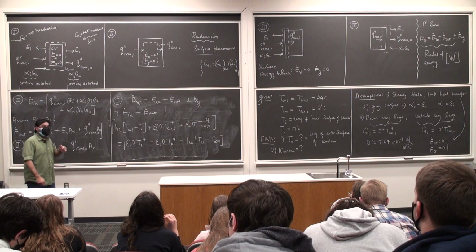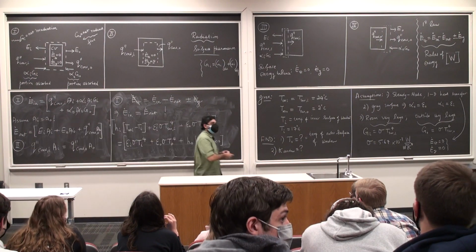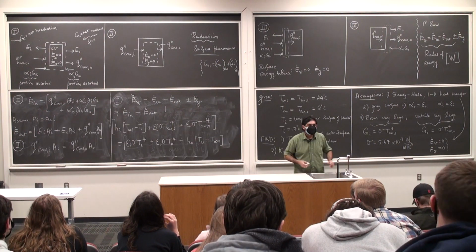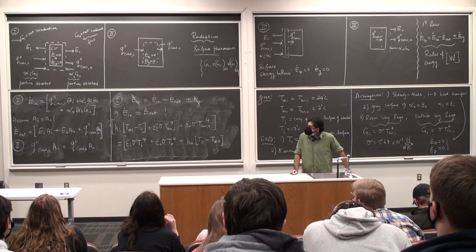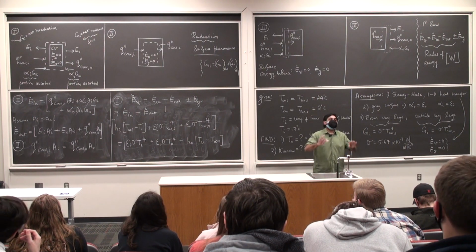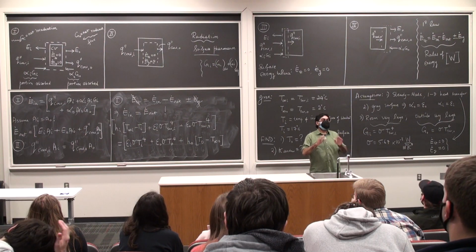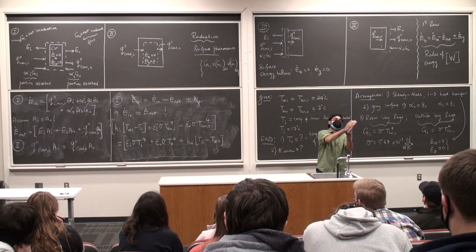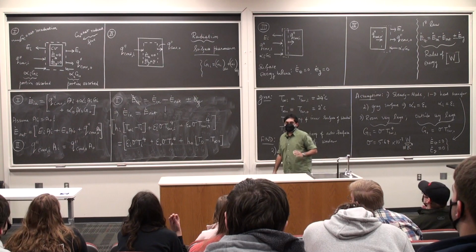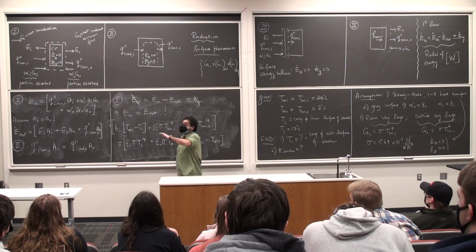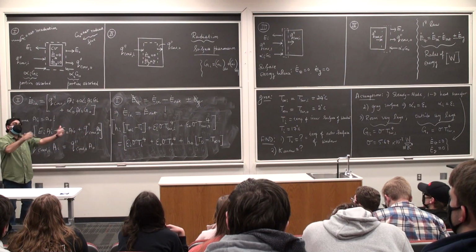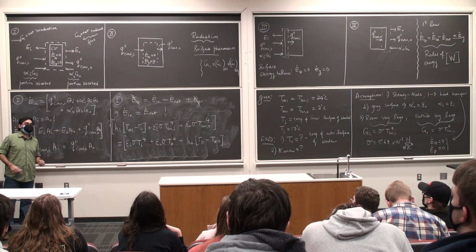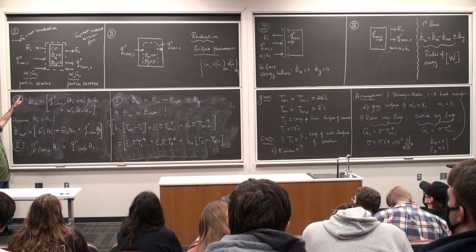As I typically do, yes, question, go. So, real quick question. Can you explain why EI and EO are both leaving the surface instead of one of them entering and one of them exiting? Oh, they are all emitted by the surface. Okay. So, whichever is the surface, you just draw an arrow that is going out of the surface. E is always radiant flux emitted by the surface. G is a portion that is absorbed by the surface. So, all the G's will be coming in, all the E's will be going out. Makes sense. And that's only if I draw my control surface that way.